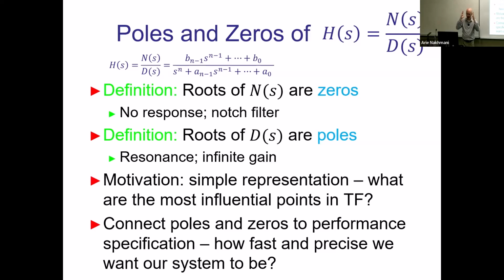If you're thinking about absolute value of the transfer function, it's gain. So if upper polynomial equals zero, zero divided by anything is still zero. So you're practically multiplying that frequency, no matter what amplitude of that signal is, by zero. So your output for that frequency will be zero, which means it's a notch filter.